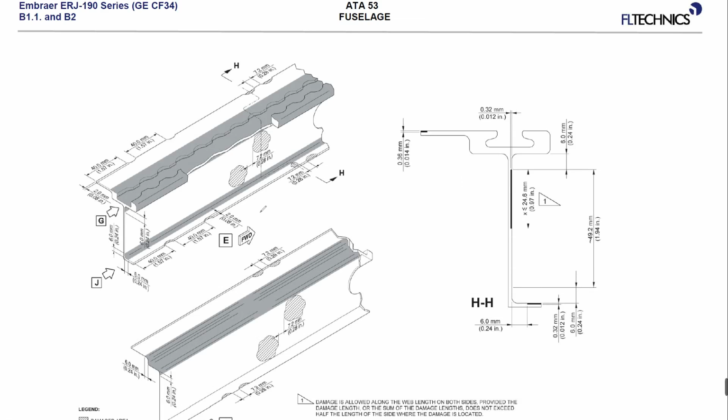Corrosion grows very easily here because when we install the seats, we use only a very short distance and the rest of the seat track is just open. These seat tracks are always full of garbage and dirt, and this dirt absorbs moisture. This moisture stays here all the time and sooner or later causes corrosion of the seat track.